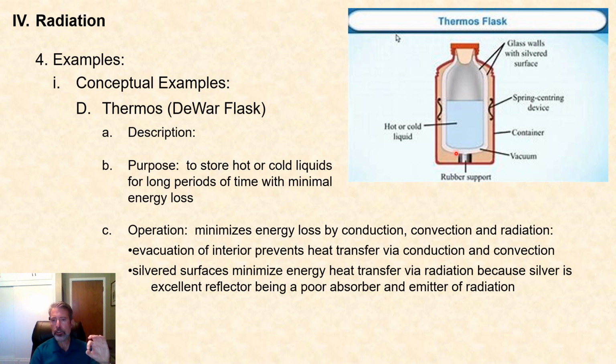So the evacuation of that chamber region means that you are going to minimize or eliminate heat loss through both conduction and convection. I don't know if any of you have ever had the experience of dropping a Dewar flask, but when you drop it, they have a tendency to explode. That explosion is what happens when that vacuum is being broken. It creates a very loud sound when the Pyrex shatters.